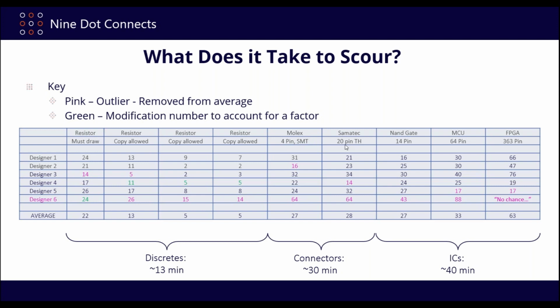Of course, the biggest issue with them is not necessarily the symbols, because the pin number and the pin name are the same, right? So you can use the array tools to put those together rather quickly on the schematic side or the symbol side. When it comes to the footprint, you're not going to find too many connector footprints in the IPC compliant footprint wizard. As a result, you're going to have to make those manually, and that's probably what took up most of the time here.